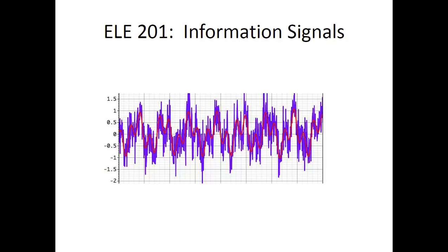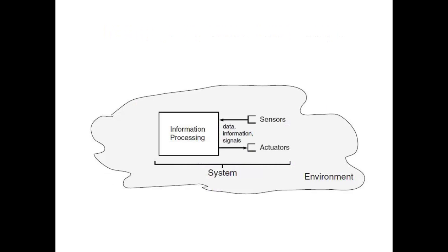Can you think of another smoothing technique that's not average, or at least not the normal mean? Okay, that is to use the median. So the local median is a way of doing smoothing that removes outliers. If you have something that's far away from your true signal, but it infrequently occurs, then it'll be removed completely by the median filter. It's a very useful filter. However, it is out of the scope of what we'll learn in this class, so there are limits to what we learn in this class. It's very, very broad, but limited.